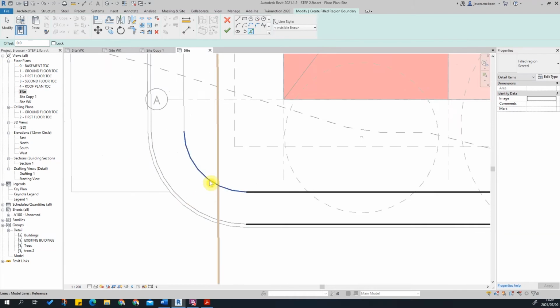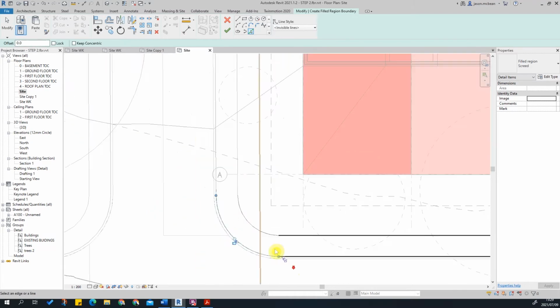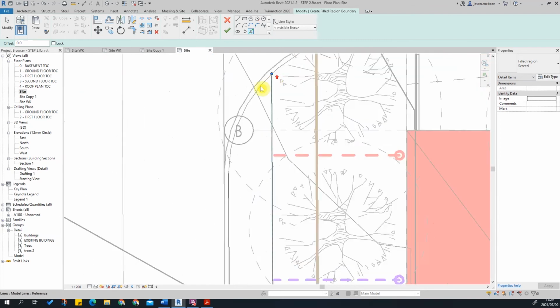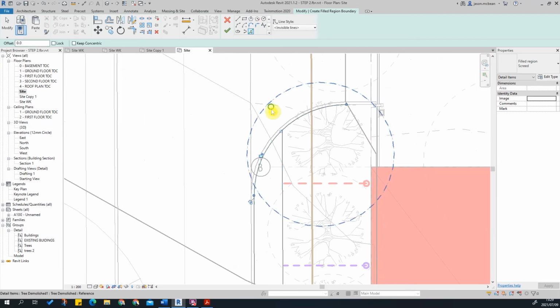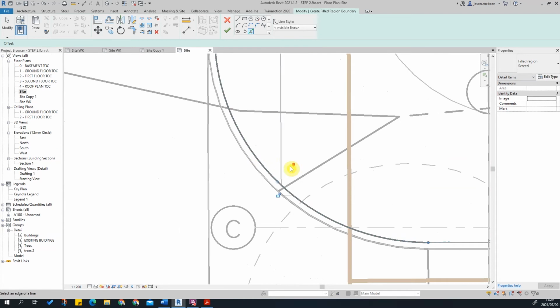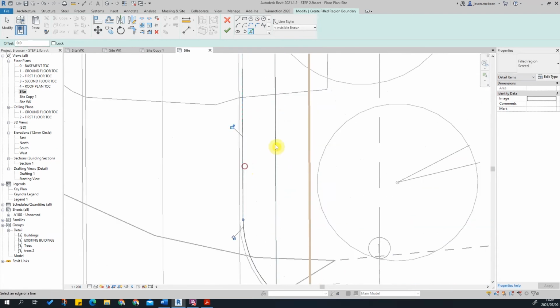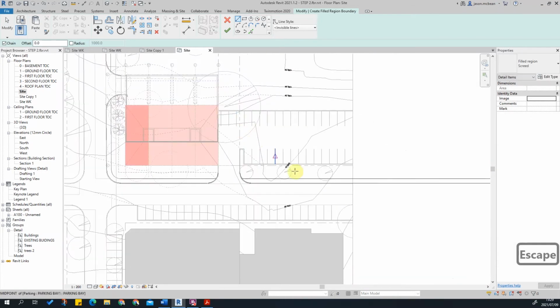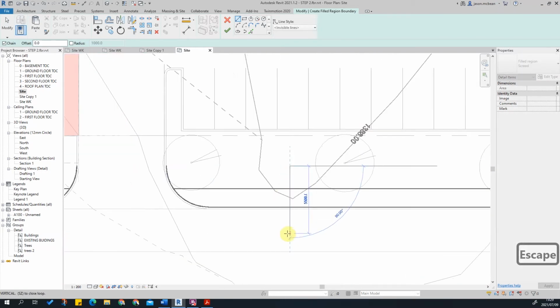This will look different. It'll look slightly grayed out. That's fine. But what's neat is it never prints. Okay, it's never visible in the view. So here, we start here again. I'm just using the pick line tool, and let's just draw this across here because this will stop here somewhere, and do that likewise here.